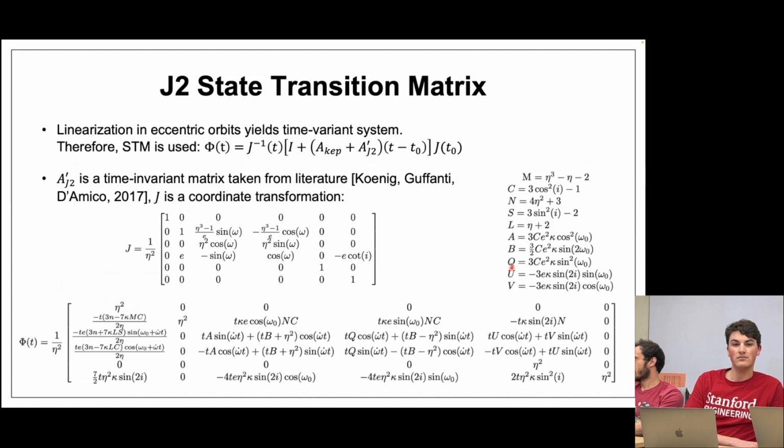Actually, for Keplerian motion, the only second order effects are in the difference in semi-major axis. So it's not a small separation assumption across the board. Not for propagation, but for mapping to the position. So for ROE propagation, this is valid for pretty large separations, but not necessarily for the mapping from ROEs into the RTN frame. Yeah, that's important to note here.